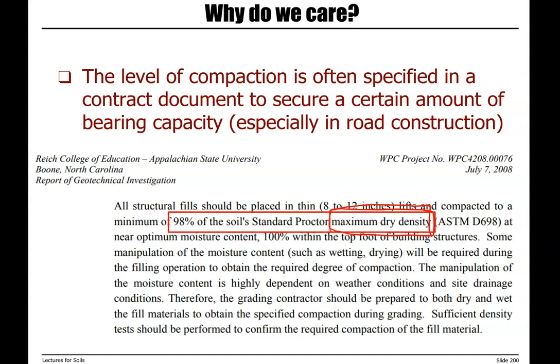So this section that you see here is from a geotech lab report, and it has a recommendation: all structural fill should be placed in thin lifts and compacted to a minimum of 98% of the soil's standard Proctor maximum dry density at optimum moisture content.